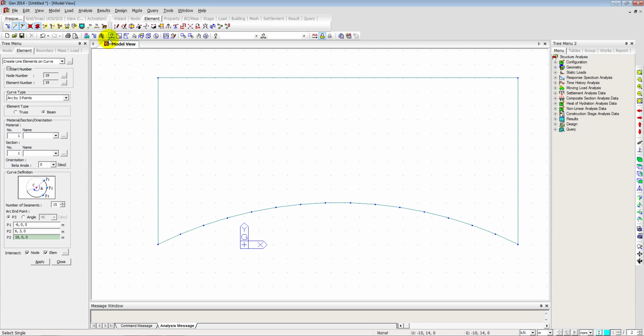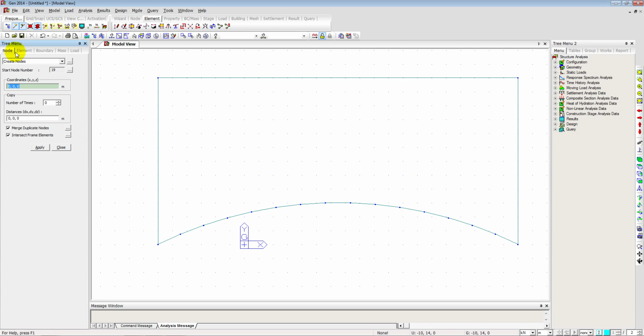Now that I've created the boundary condition, I'm just going to create some nodal points for some of the columns going up through. So just a basic floor plan, so columns every 4 meters or roughly about that. We just want to have them going along the inside of the building, so making sure they're all in equal distance.